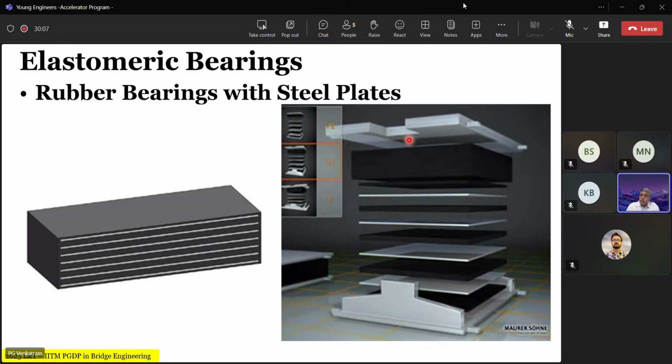So with elastomeric bearing, you can also create boundary conditions within the bearing design and detailing that will permit controlled movements, controlled deformation, control in one, free in other, control in both, free in both. All these possibilities exist purely depending upon how you detail the top and bottom plates.